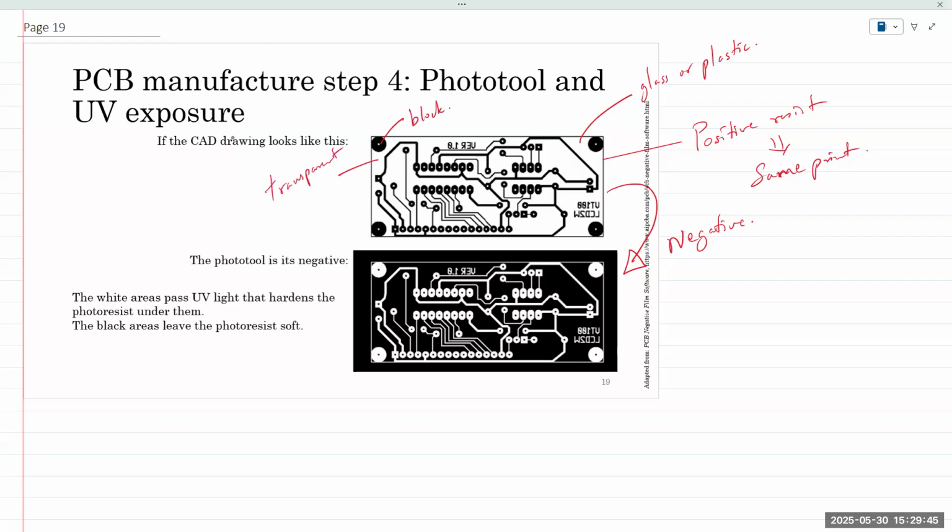All right. So now let's say you take this plate. You take this plate and you put it right on top of your photoresist coated sample. Your sample is coated with photoresist material. You put the plate on top, and you shine UV light through it. The light will be blocked in some areas and it'll be allowed to go through in the transparent areas.